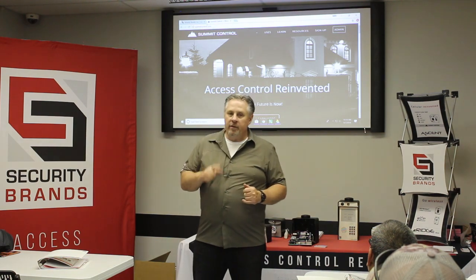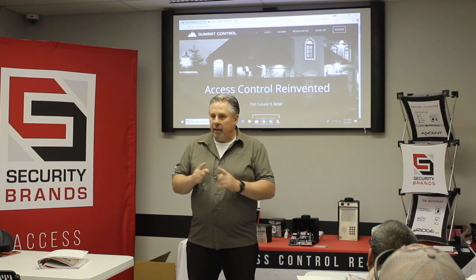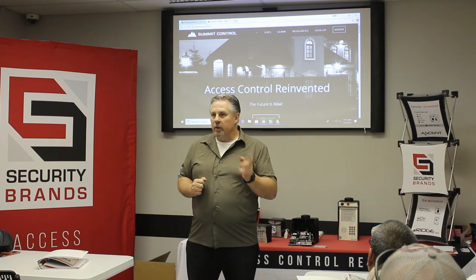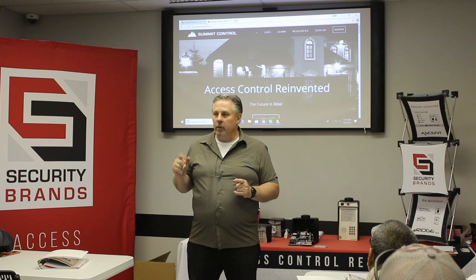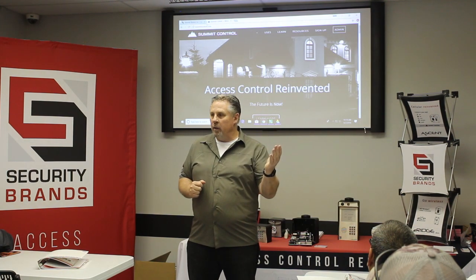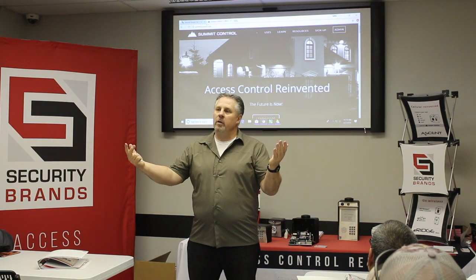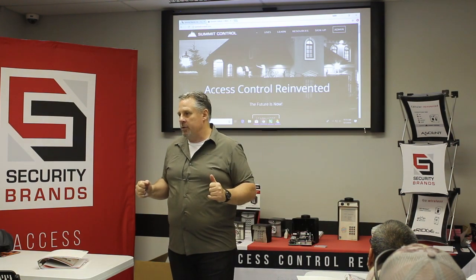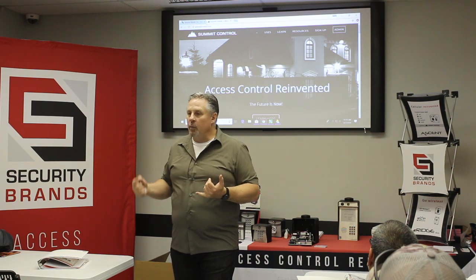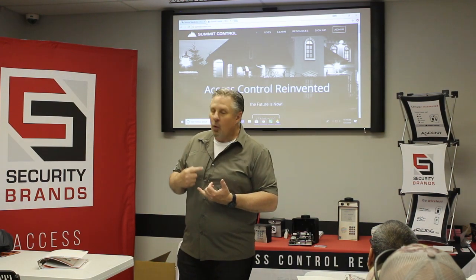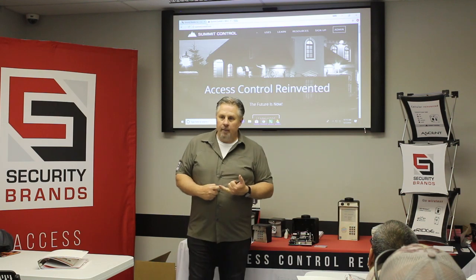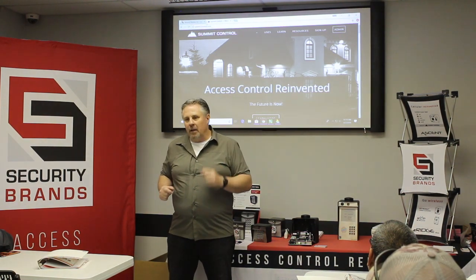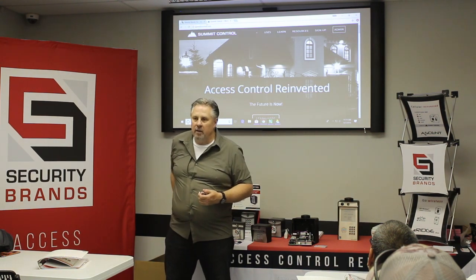1251, and then instead of 1, you use the number 100, and then in a block format you can program up to 2,000 cards. So 1251, you get a beep. 100, you get a beep. 0001 for card 1, 2000 for card 2000, and you just did a block format, putting 2,000 cards on the card reader. Card readers are available from me in HID or secure key, so it's however you want to go. They're relatively the same price. Secure key has a little bit better range than the HID.